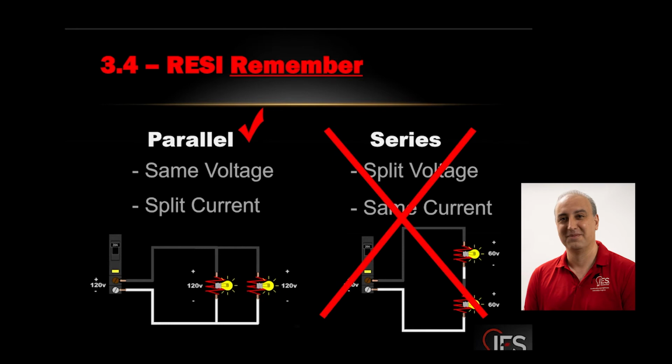Well, again, that's why some of them are insulated, but the ground, if you wire the system correctly, should carry current for a split second. Breaker should trip and stop all voltages in that system. And, you know, odds of someone touching that wire while it's tripping, it's next to nothing. So that's why, with ground, a lot of times it's just the bare copper. But the neutral, this is a common mistake that rookie electricians make. They think neutral doesn't carry current or has less current. Neutral is same as hot, right? Actually, let's look at our circuit here.